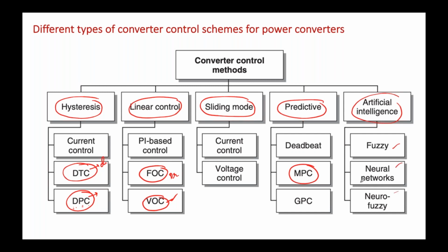For electric vehicle applications, they are still using conventional methods as well as model predictive control methods. Field orientation, direct torque control and model predictive control methods are being adopted in electric vehicle applications to control the torque instantaneously. With respect to the controller, they are trying to bring the torque expression into linear mode. Once your torque is linear with respect to the controller, we can improve the torque profile of the AC machine similar to a DC machine. That is the beauty of this control scheme.